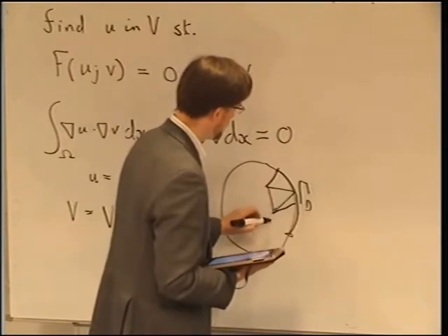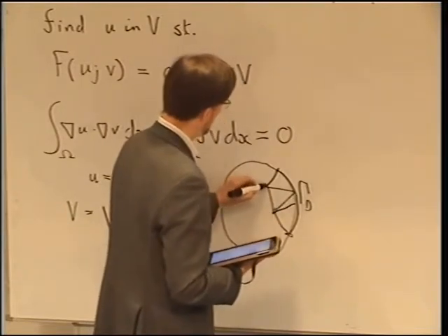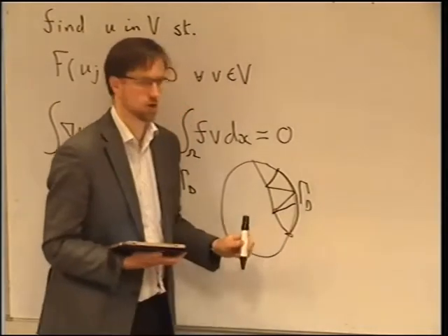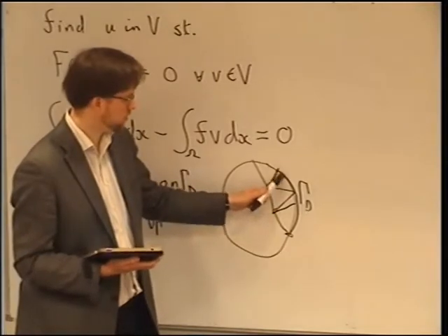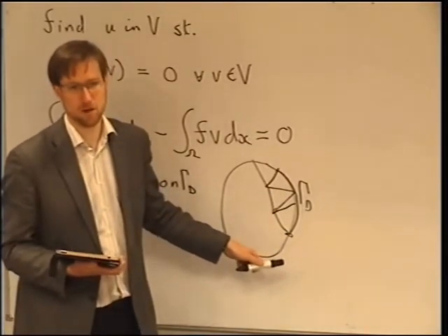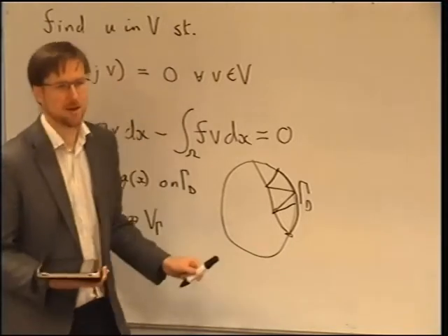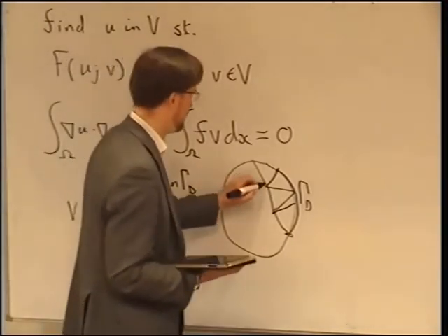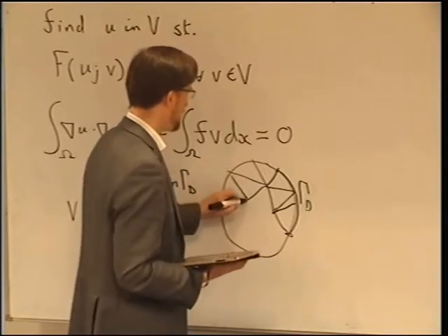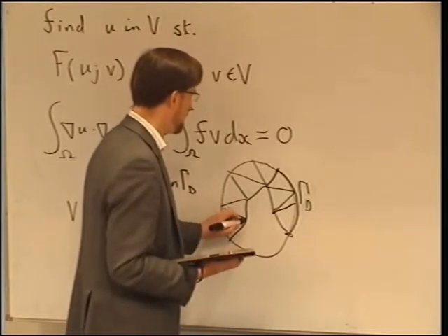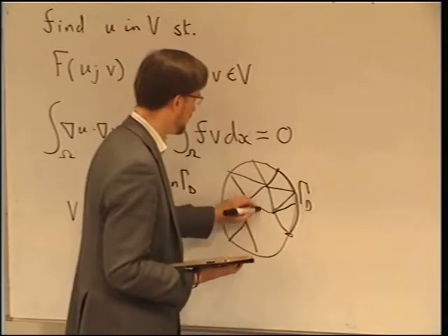That's not a very good triangulation, that's a bit better. In all practical implementations, it will be a requirement that whichever chunk of the boundary you're using for a boundary condition, that coincides with mesh points. It's an incredible pain to do that in any other way, and since you normally control the mesh generation process to some extent, there's not really a lot of point in trying to do the hard problem.